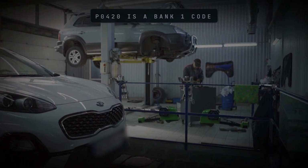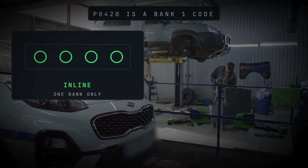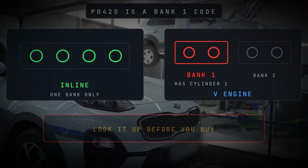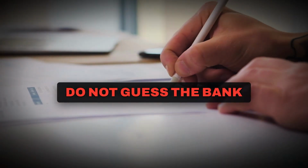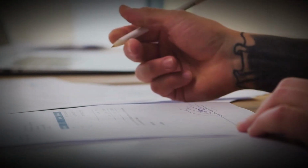P0420 applies to bank 1. On an inline engine, there is normally only one bank. On a V-shaped engine, bank 1 is the side that contains cylinder number 1. Do not guess which side that is. Use service information for the exact engine before buying any bank-specific component.